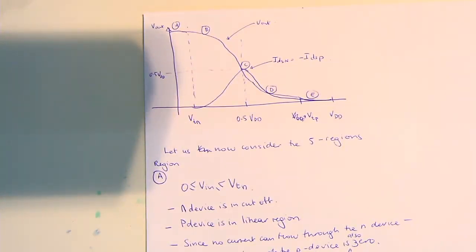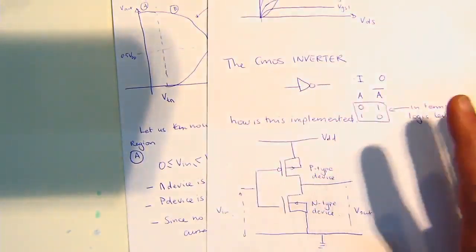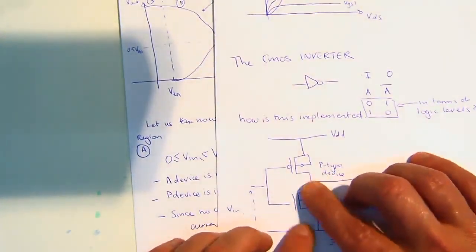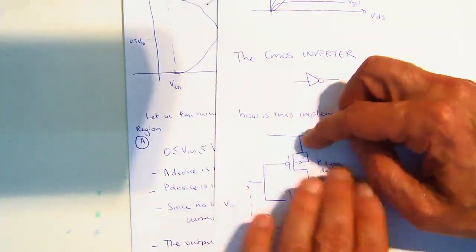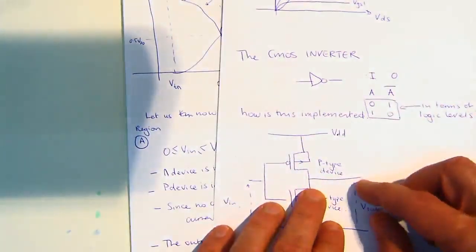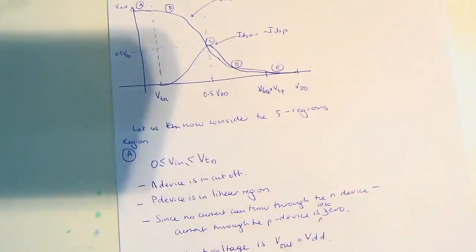Okay. And the output voltage is? Almost right. What's the output? What's the power voltage? Right. Now you can think of it in the simplest of terms. For argument's sake, and this is very simplistic, this transistor is open. You can think of it as a switch: that one's open, that one's closed, right? So therefore what you see at the output is VDD. Okay? Excellent.